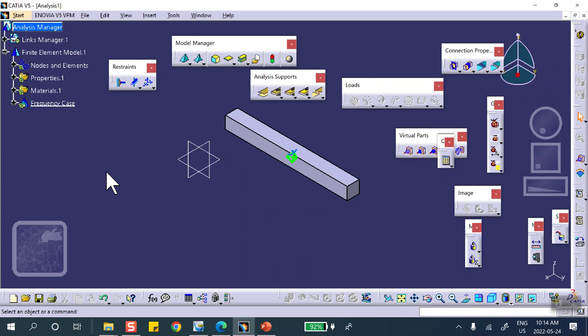light up. Okay. And I noticed in the lab, and this may happen to you at one point, that if inadvertently, whatever it was down here, whether it was a frequency or a static, you deleted this, notice that both the restraint and the load are gone. And the question was, what happened to these? I can't do any more because you deleted that inadvertently. No big deal. If you want, you can always put it back in.